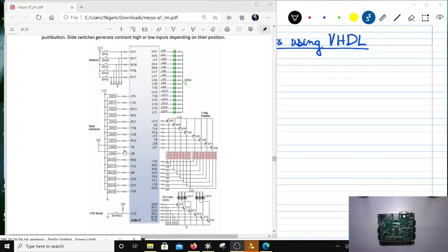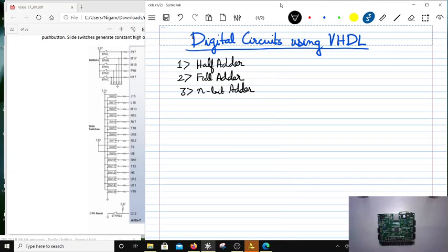This diagram shows the FPGA pin numbering. Now how is this done? I'll tell you. An FPGA package has ball grids, it's a ball grid array, and it goes both ways, with rows and columns. These pins are labeled this way. You can go 1, 2, 3, 4 and like that, and then you can go A, B, C, D like this. So you go alphabetically this way and numerically this way. A particular pin is going to be a particular letter and number, for example C2.